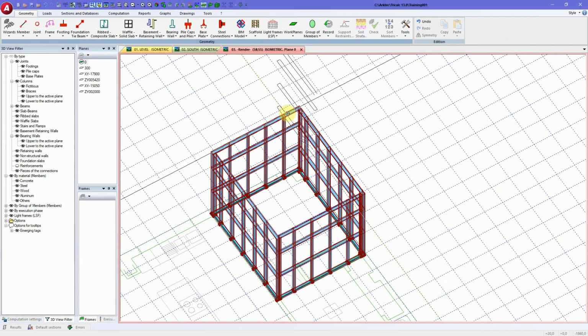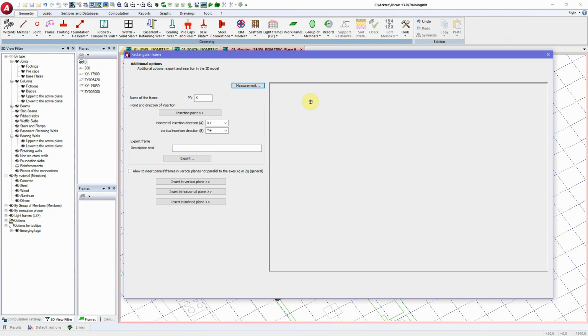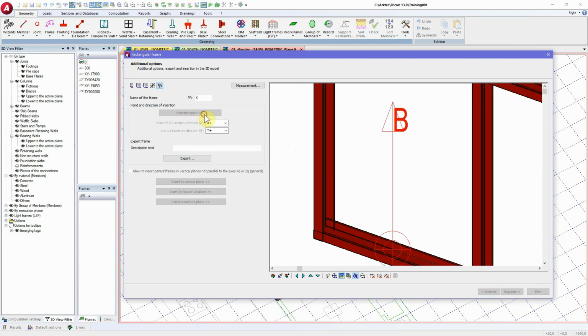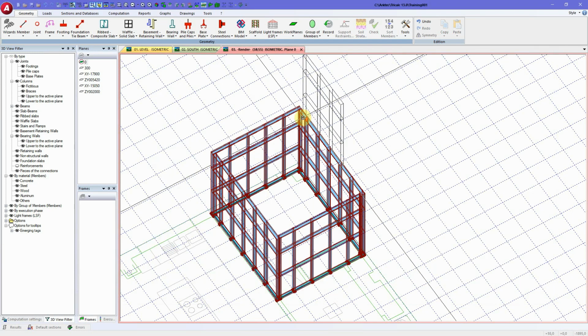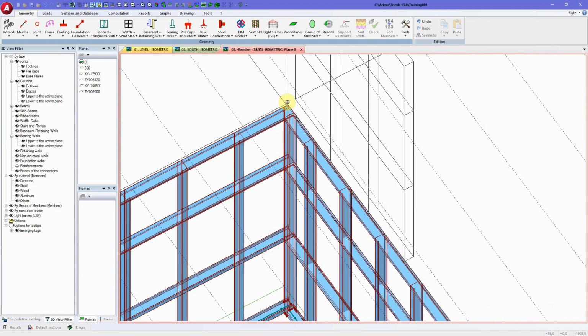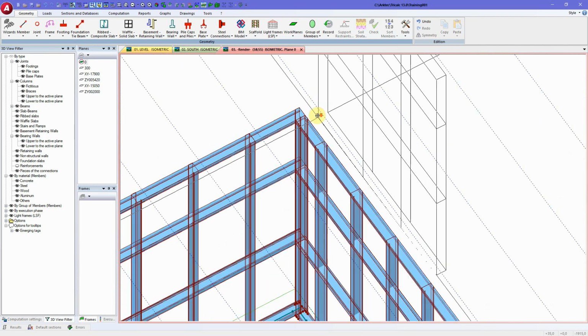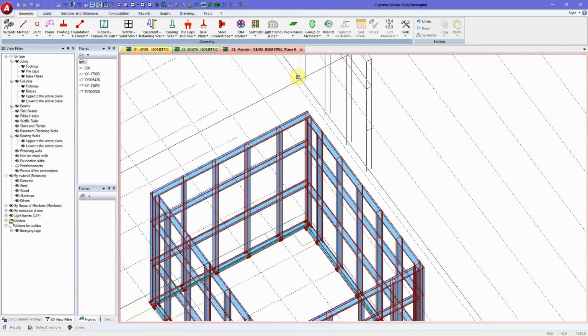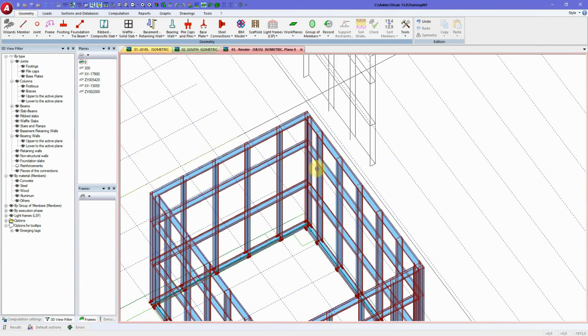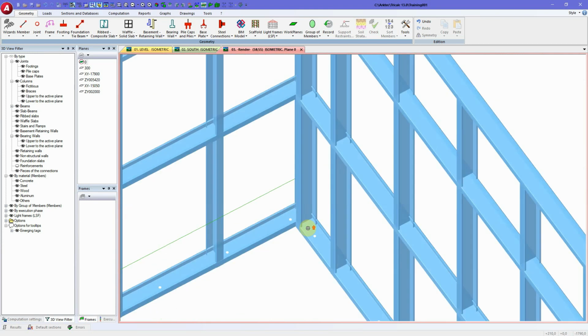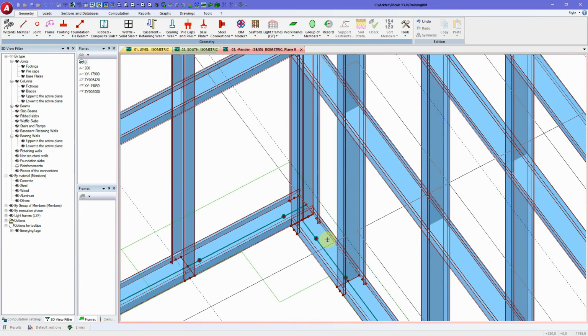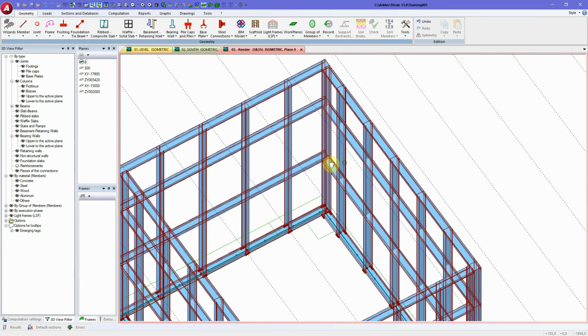This way you are going to create the insertion point. Let me change the insertion point here to another place. I'm going to search here, for instance, for this corner. Okay. And I will place it in a horizontal plane. This way, when we select the point of insertion, I will select that corner. Pay attention that we have selected the plane 0, and you see the vertices here. The vertices are here to select, but they are not here on top.